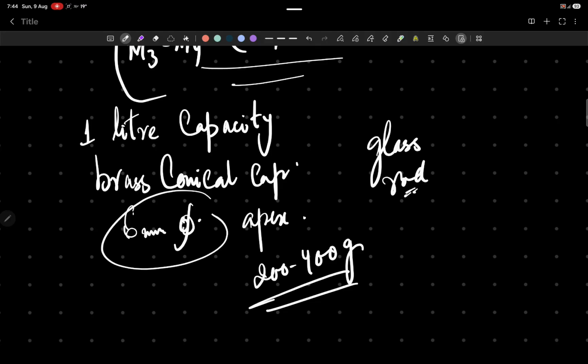More and more water is added, and the stirring process is continued till the picnometer is filled flush with the hole in the conical cap. Then the picnometer is wiped dry and weighed. The picnometer is then completely emptied, washed thoroughly, and filled with water alone, flush with the top hole. It is wiped dry and weighed, and then we find M1, M2, M3, and M4.